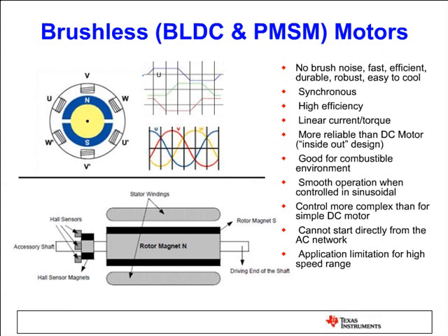And the good thing about these motors, again, we don't need brushes, so we don't observe audible noise or electrical noise or sparks or EMI. And these brushless PM motors are synchronous motors, which means that when you energize the stator, we create a rotating field in the air gap. I'm going to talk about this later.